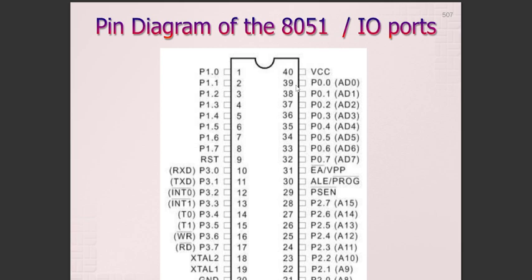When P0 is configured as a port, unlike other ports whose pins have a built-in pull-up resistor connected by this end to plus 5 volts power supply, the pins of this port have this resistor left out. Input configuration: if any pin of this port is configured as an input, then it acts as if it floats. That is, the input has unlimited input resistance and indeterminate potential.